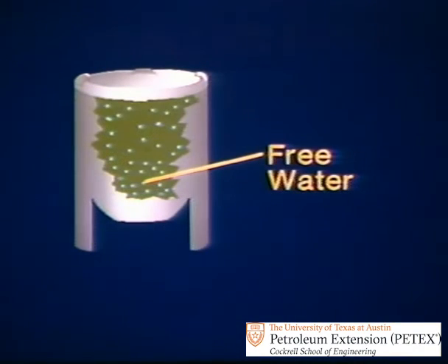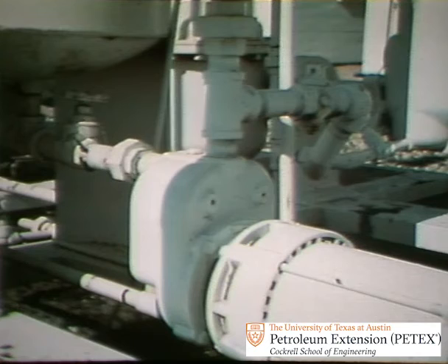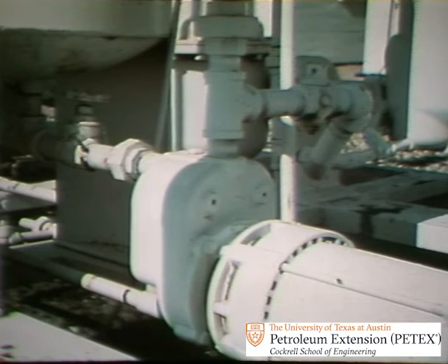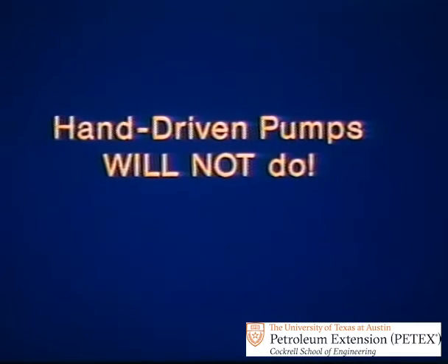Whether the receivers are portable or fixed, the sample inside needs to be properly mixed to ensure dispersion of free water and to eliminate stratification. Otherwise, a misrepresentative test may occur. So, the sample receiver must be equipped with an effective power-driven mixing device. Hand-driven pumps or hand-driven mixing devices won't do the job. Few hand-driven devices are ever operated long enough to be really effective.